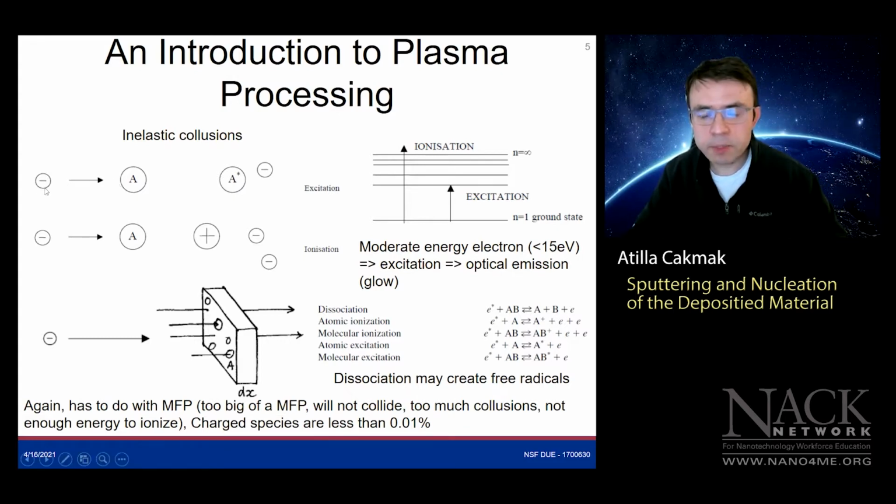We're going to speed up the electron up to some extent, and then we're going to hit this gas atom at that speed so that we will deliver the energy and try to knock off an electron and set it free. So we will start with one electron, and then we'll generate another electron. That's going to make a secondary electron, as we were calling it within the discussions of SEM as well, the secondary electron generation there.